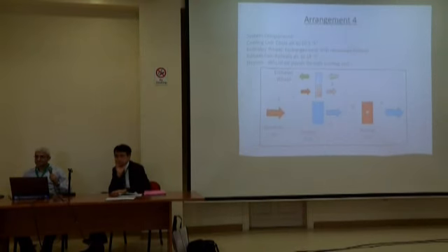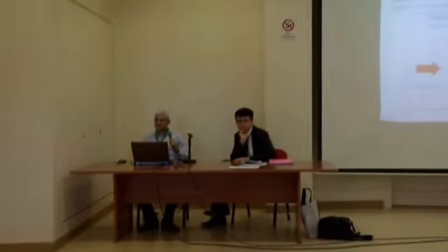Thank you for your presentation. I was just wondering, what's the main difference between an enthalpy wheel and an energy wheel? And how sustainable is such a configuration in terms of efficiency and running cost? The sensible wheel transfers only sensible heat, while the enthalpy wheel transfers both sensible and latent heat. It has a material that can absorb heat and humidity from one side and dissipate it to the other side.